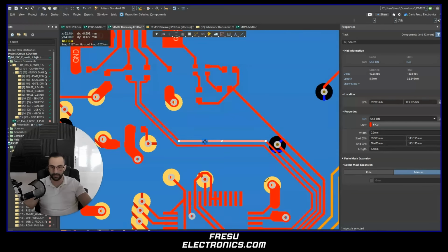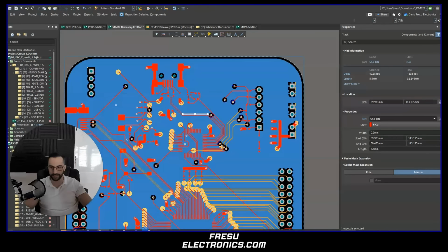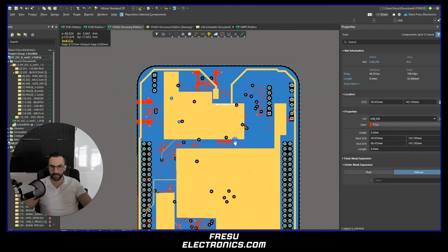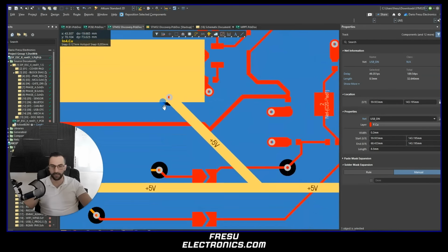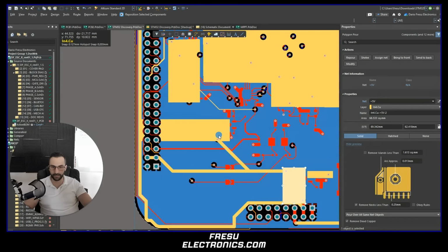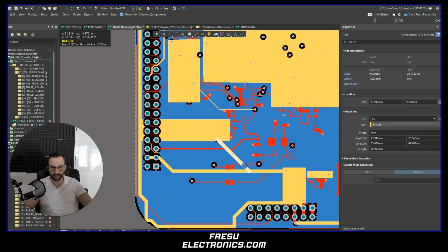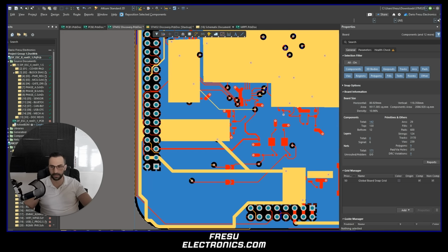Then let's go to problem number 10. Problem number 10 is creating antenna-like structures. What do we mean by that? Maybe we can choose another layer here. Antenna-like structures can be something like this, where we have this part in here, which is a plane, this part in here, which is another plane, but then we have this small signal trace, which is connecting the two points. The problem with these two is that in here, we're going to have a voltage.